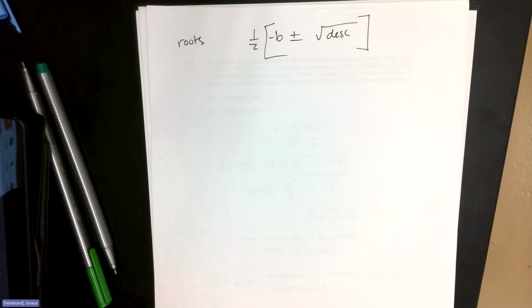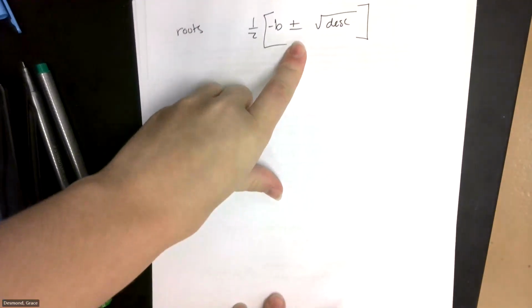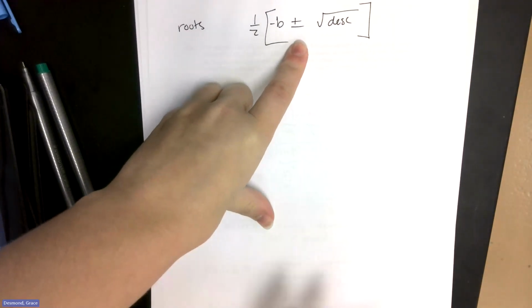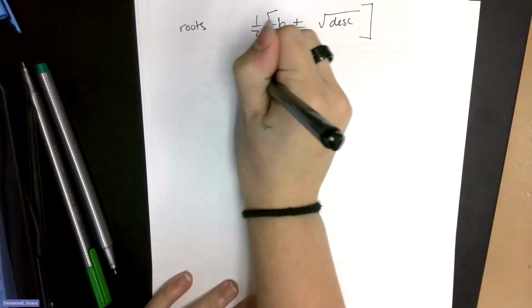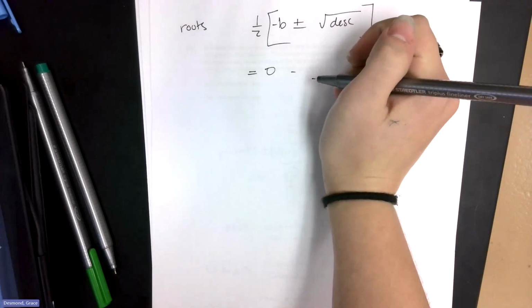That table, y'all are looking at the table, right? If you look at those graphs, you're saying that they are equal. Then the only time they're ever going to be equal is if there is nothing in that discriminant, because it's plus and minus. If that is 0, that's the only time they're ever going to be the same. So if it's equal to 0, then it's critically damped.